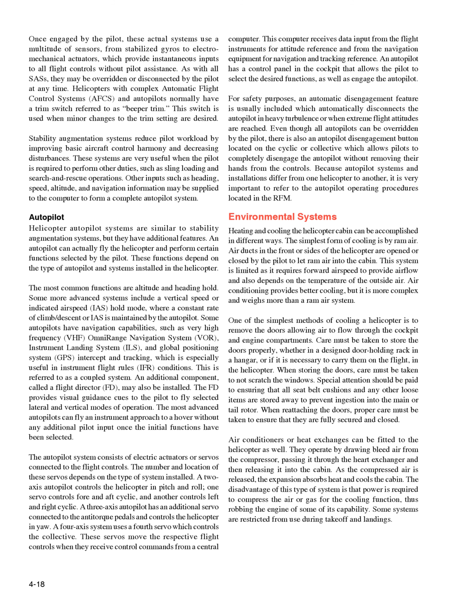Some autopilots have navigation capabilities, such as very high frequency VHF, Omni Range Navigation System VOR, Instrument Landing System, ILS, and Global Positioning System, GPS, intercept and tracking, which is especially useful in instrument flight rules, IFR, conditions. This is referred to as a coupled system. An additional component, called a flight director, FD, may also be installed. The FD provides visual guidance cues to the pilot to fly selected lateral and vertical modes of operation. The most advanced autopilots can fly an instrument approach to a hover without any additional pilot input once the initial